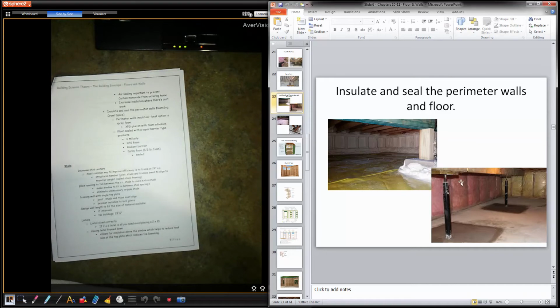As you can see, it's basically full coverage insulation right to the plate. Fiberglass, which is going to absorb moisture, but it's common. Like any house built 10 years ago, that's the way they were doing it. Right? Fiberglass in the basement, 6 mil poly in the basement. So my opinion should be rock wool with a smart vapor retarder nowadays. But pretty typical if you go into a house to see this kind of a thing.